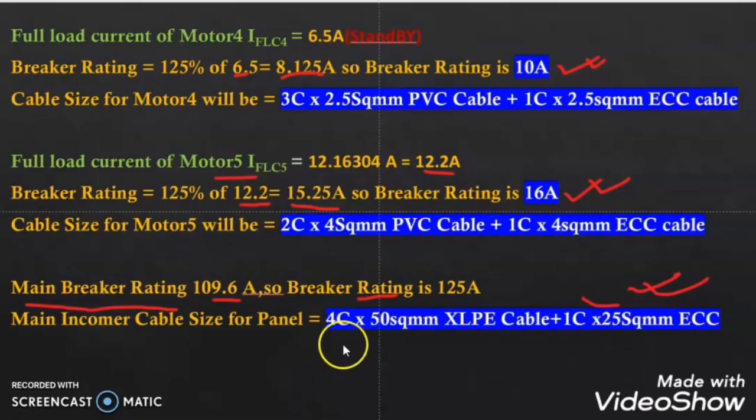So the final incomer cable size is a 4 core 50 square mm XLPE cable, and as we know, the ECC cable will be half of the phase cable after 35 square mm. So it is 50 square mm, so the ECC cable will be 25 square mm.